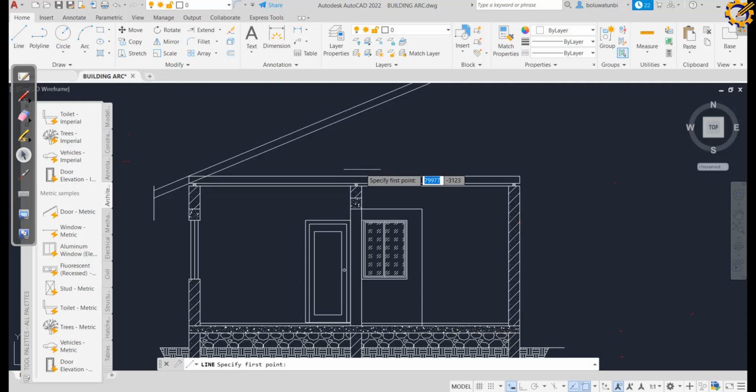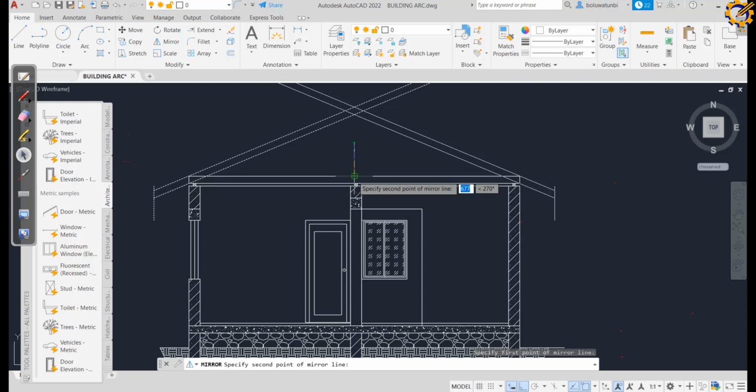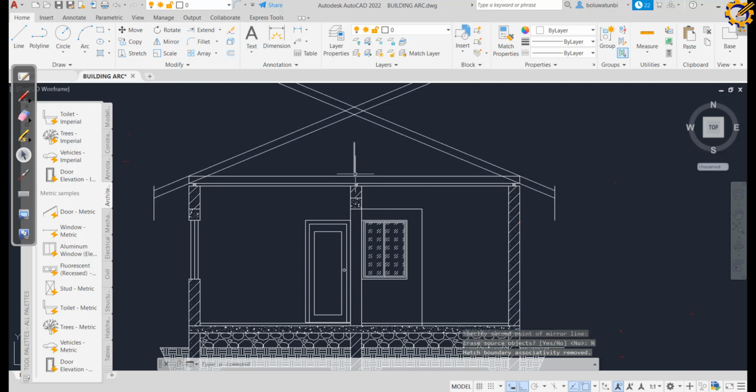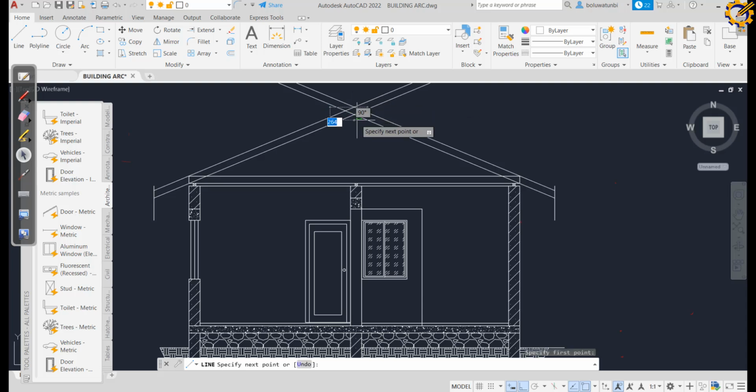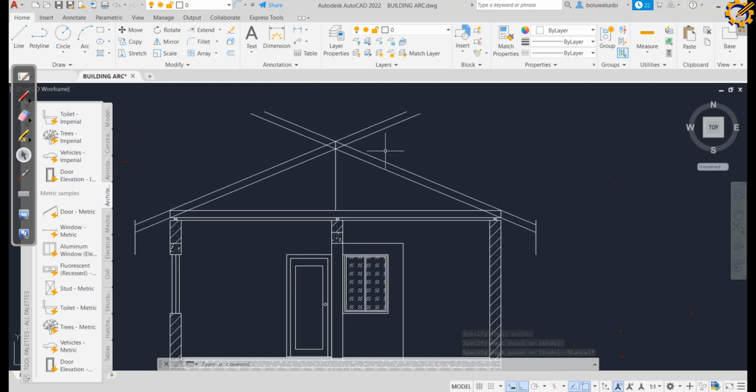So after that has been done, I can actually mirror this to the other side. Let me just create a center line here like this. Bam, that's my center line. So highlighting this and this with my mirror command, I come here and here, then I click on no, so I have it mirrored that way. Okay, so I can draw this from that midpoint all the way down here like this. So we are getting there, right? Check. So I've drawn my wall plate, my tie beam.